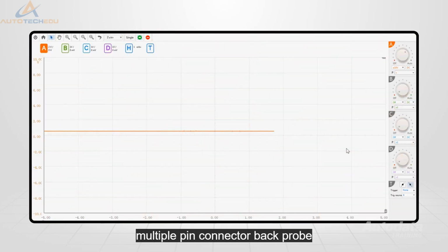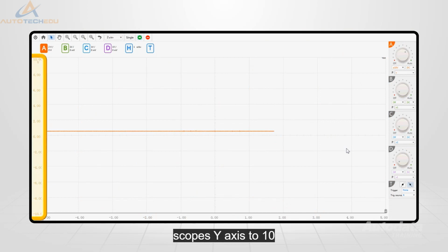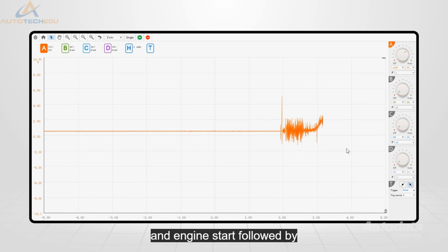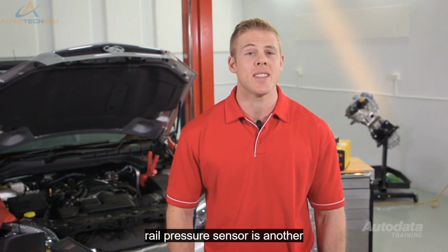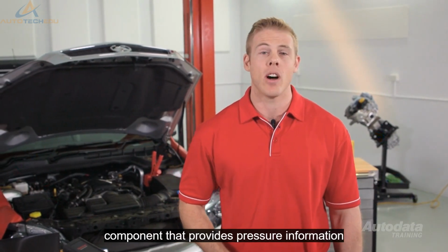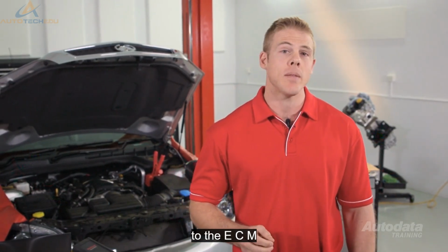On a multiple pin connector, back probe the signal circuit and the other to ground. Adjust the scope's Y-axis to 10 volts and the X to 2 seconds. On this vehicle, we can see the trace at key off, key on, and engine start, followed by an increase to 4,000 RPMs.